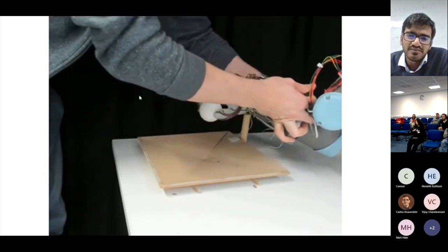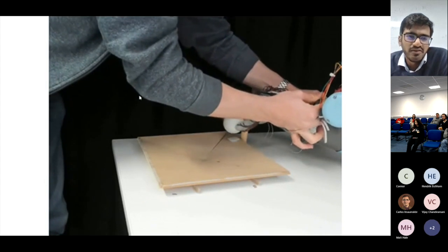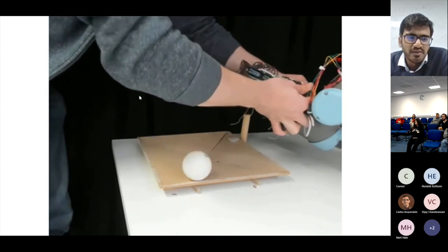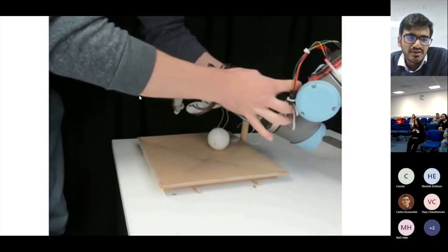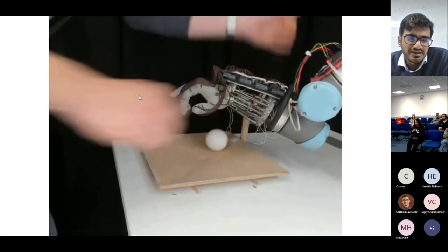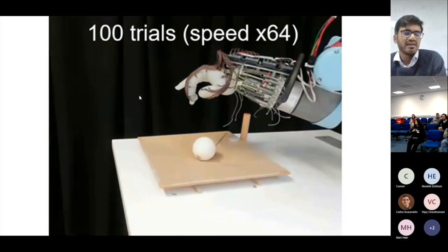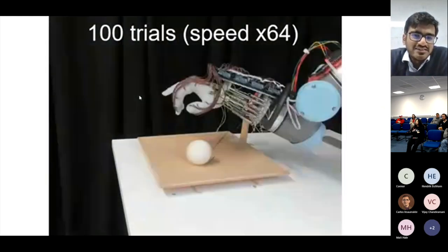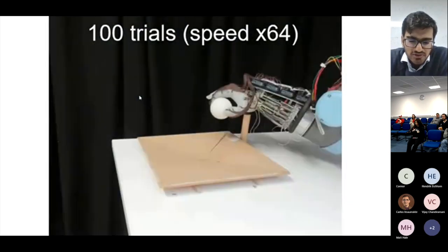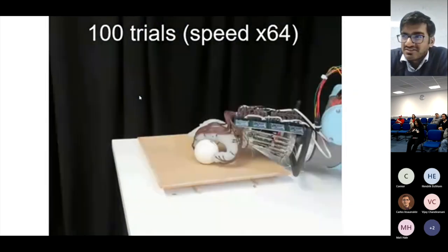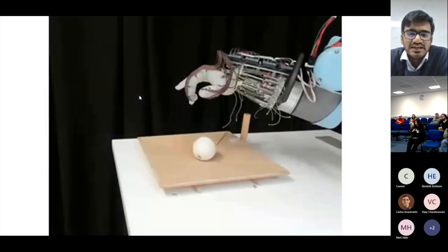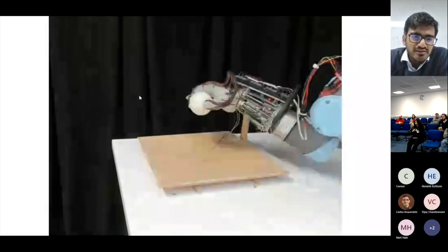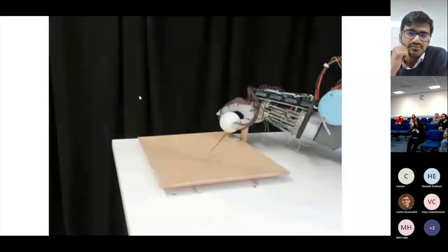The hand itself is passive, so you can just record what happens to the encoders in the rigid robot, teach it once how to pick it up, and then once this trajectory is saved, the robot can essentially repeat these things multiple times. So it's very easy to teach it how to use the manipulations, and it's easy to teach it because one is because of the anthropomorphic nature, and also because of some of this passive interaction that we can do with the soft hand.